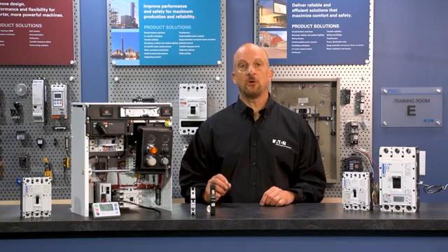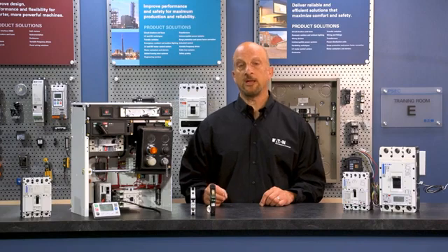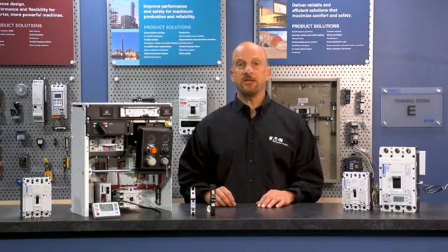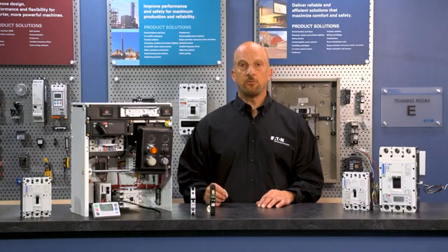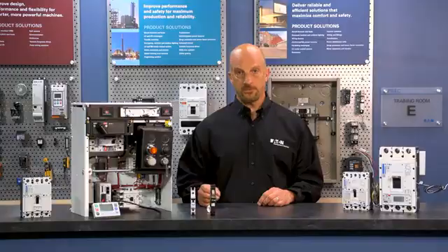There are a number of circuit breakers that are used in special applications that are slight variations of standard breakers. We will discuss a few here, specifically HMCPs, supplemental protectors, AFCI and GFCI breakers, and DC breakers. HMCPs are a special breaker used in motor control centers. These motor circuit protectors offer only instantaneous fault protection, but do not have an overload protection like a normal thermomagnetic breaker. When an HMCP is used with a motor starter, the starter provides the overload or thermal protection, and the HMCP provides the fault protection.